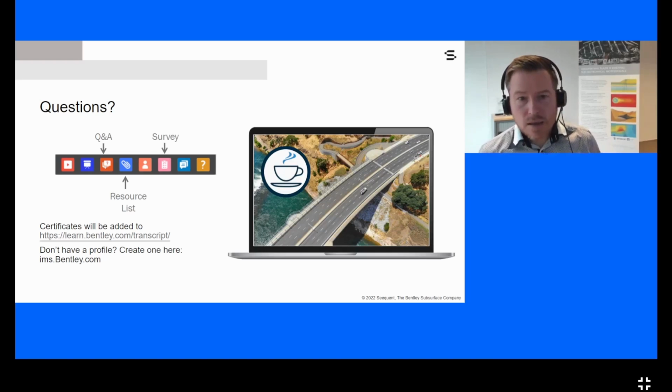So it can make a difference if you, for instance, have your soil loaded in compression or in extension or in shear. That's only possible if you have a model which has the stress history taken into account. So that can be done with NGI-ADP. But in GeoStudio, you can also have these anisotropic models, but you have to specify the direction up front.